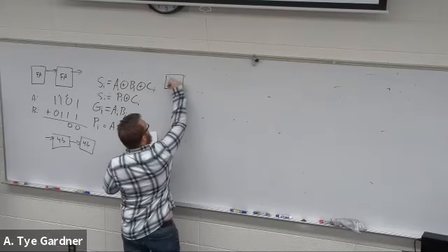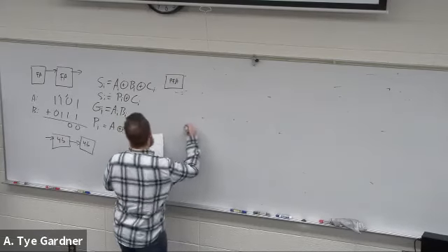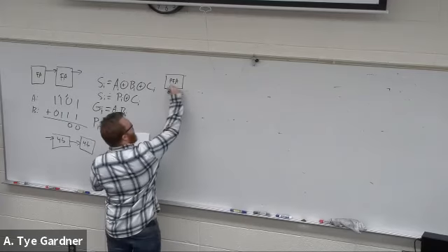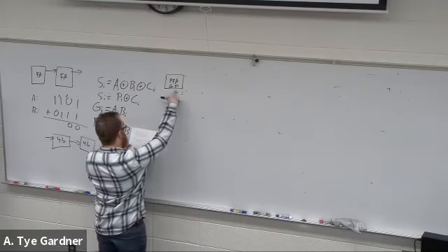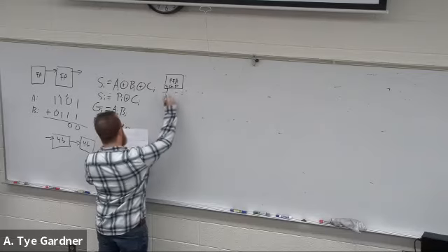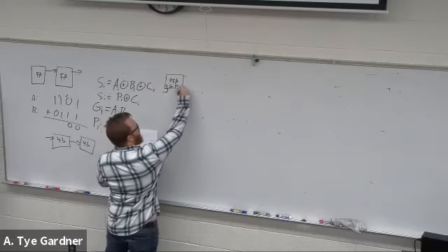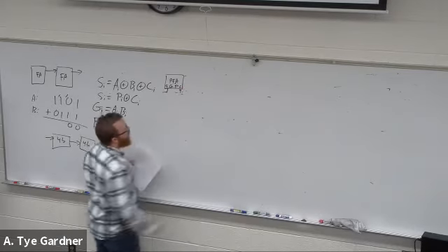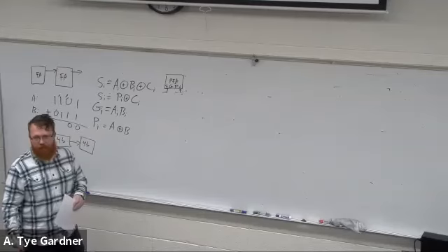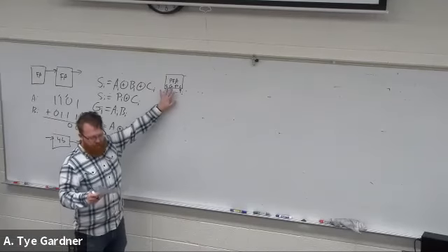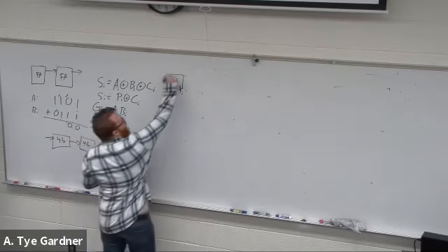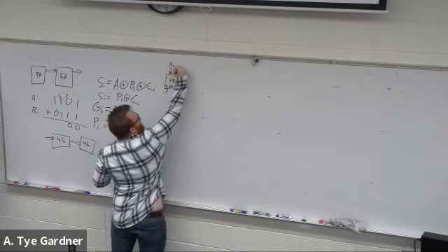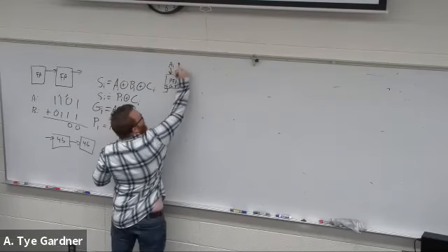they call these partial full adders, and they're going to have a G and a P, right? Generate, propagate outputs. And then it needs a sum and a carry, which is its input. Okay, and that's all. I don't actually need the carry out. And then up here, A_i, B_i.